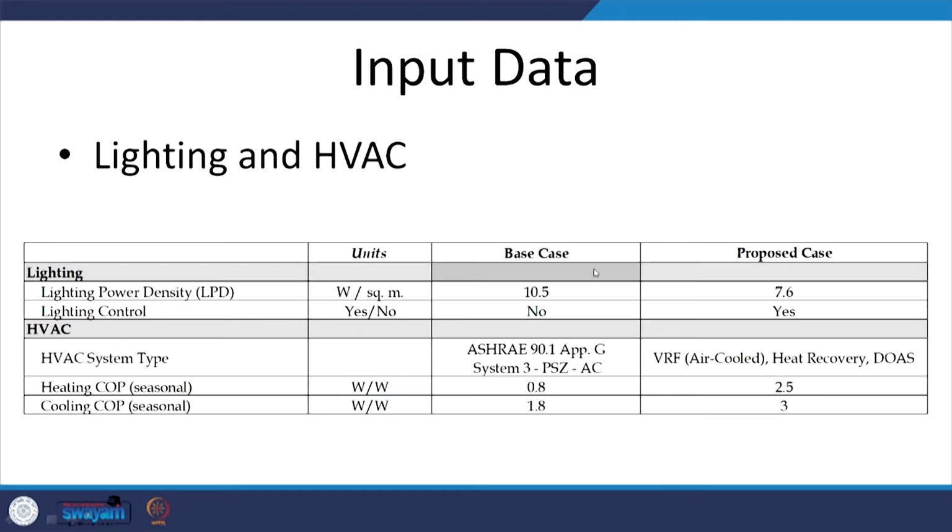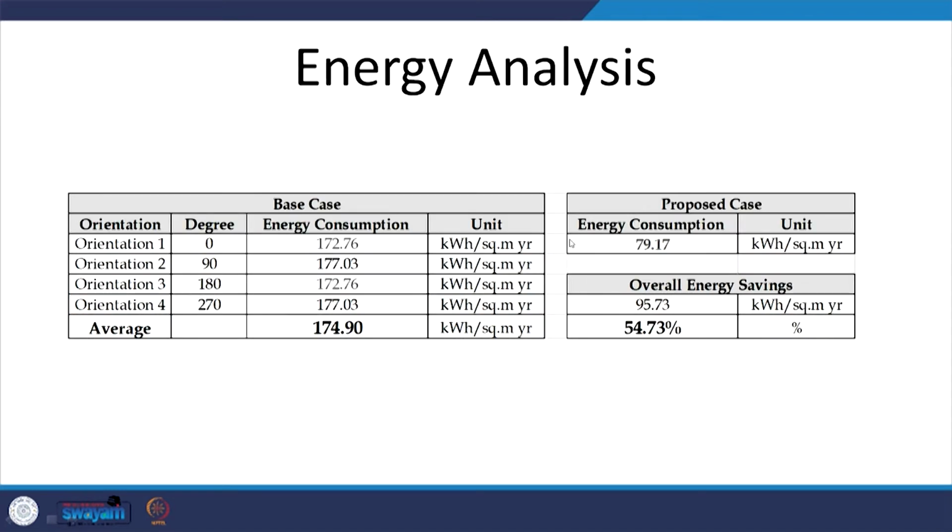We also changed lighting and HVAC, and instead of the standard values which we got from the codes, we changed it to the technology and the more contemporary numbers which are available in the market today. Once we have done the base case and we also have the proposed case, we can do a direct comparison between how the base case is performing and how the proposed case is performing with respect to the base case.